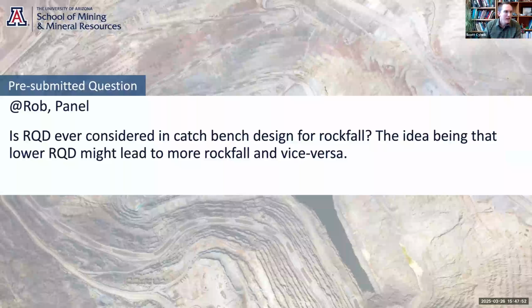Yeah, I'll just add in that, like Rob said, RQD is not necessarily the top parameter we're worried about when we're doing a bench design, but it is something that I'll always worry about when we're considering different mining increments. So for instance, if a mine is considering going from single to double benching, and if they're using cable shovels, that would be from like a 15-meter bench to a 30-meter bench.